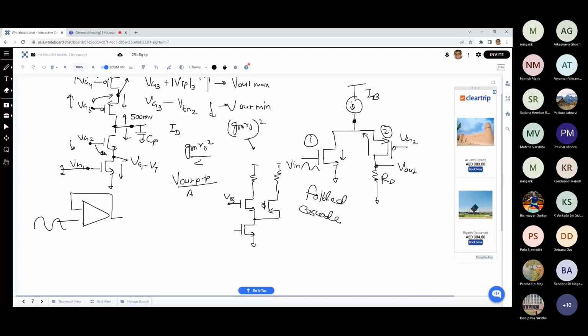Of course, the bias current over here, you have to set such that, first of all, whatever gm you require, it is coming in the first device. And likewise, in the second device also, you are getting. So the bias current here has to be adjusted properly because the same bias current is getting divided into the two MOSFETs. So here, whatever VGS and W by L you put for the M1, it will determine how much current it is going to take, how much DC bias I1 it is going to take, and the rest will flow into this one.